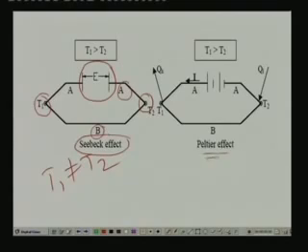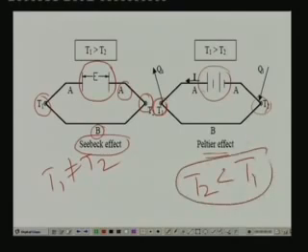Now the Peltier effect is the reverse of the Seebeck effect. Here, initially the two junctions are at the same temperature, then we connect a voltage supply and pass current through this. When a current passes through these two dissimilar materials, you find that at the junctions the temperatures become different. In this case you will find that T2 is lower than T1. As long as the current is flowing through it, there is a temperature difference. As a result, at T2 you can get a refrigeration effect and heat rejection takes place at T1. So this is known as the Peltier effect.